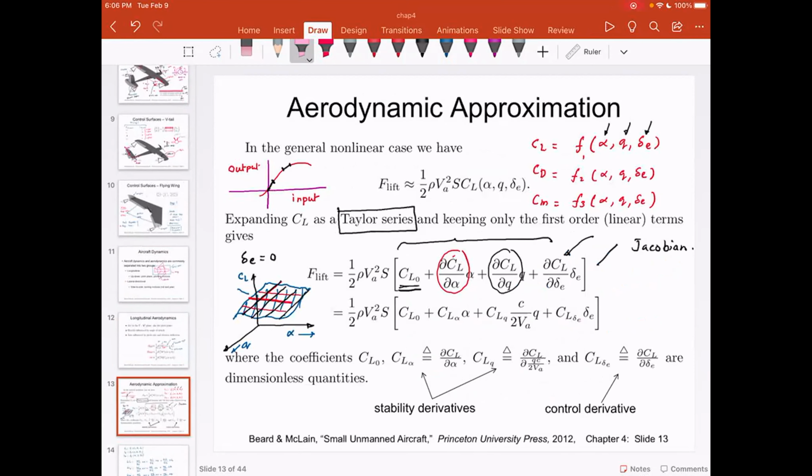But when we look at the Simulink code, we will use the homework or the code that you have written. And I will explain it to you as we go through the material. Now, I want to talk about these equations again. These are nothing but the linearizations of the lift equation. And we talked about CL, partial CL or partial alpha is nothing but the gradient or the slope of coefficient of lift with respect to angle of attack.